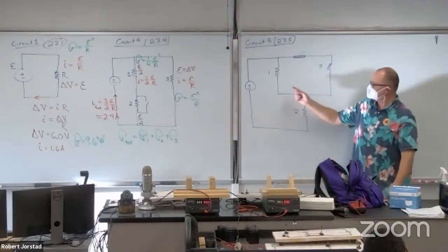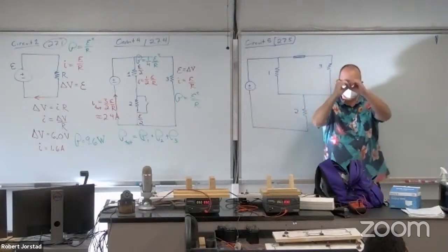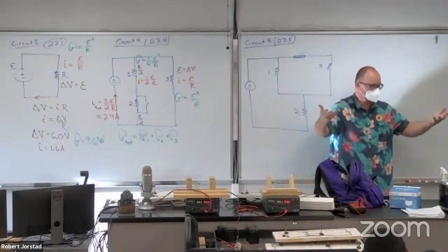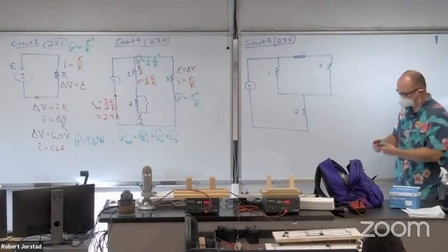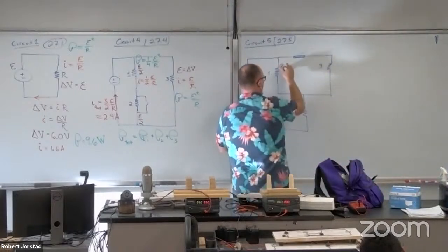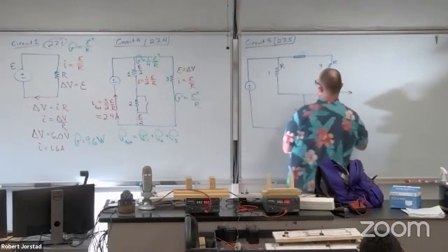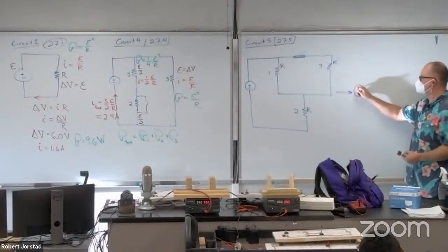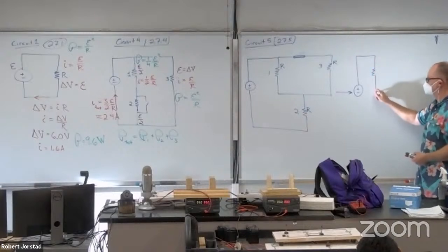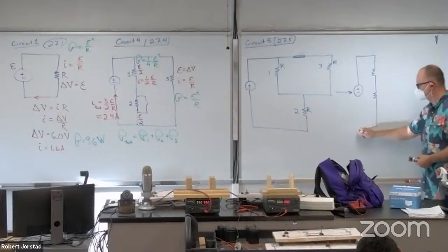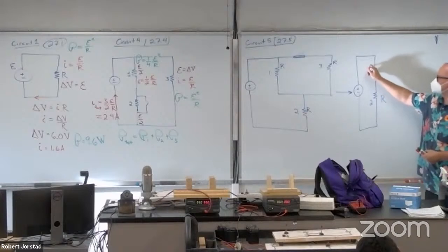Think about it like this. If I have just this one pipe, let's say it's this cross-sectional area, then I add a second pipe, that's like doubling the area. I should get more current flow. It's easier to push water through the pipe. Everybody okay with that? All right, so if this is resistance R, this is resistance R, and this is resistance R, this would be equivalent to a circuit like this, where this is number 2, that's resistance R. This is the combination of 1 and 3.